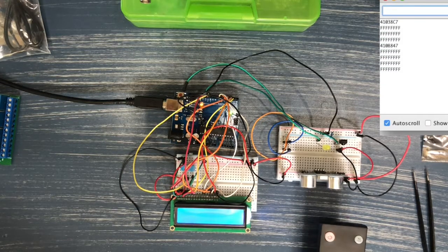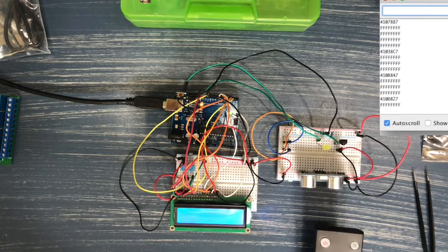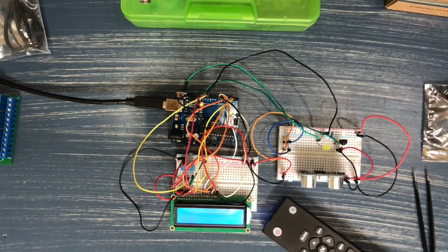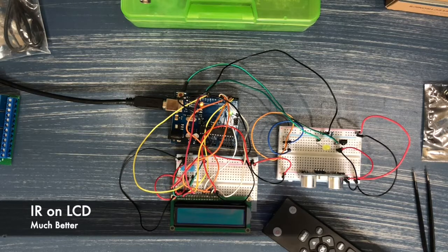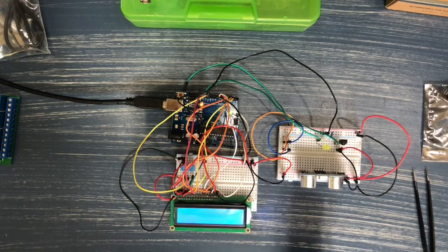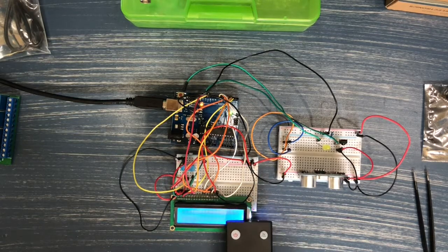There's one, you can see the code. There's a second one, a different one. There's a third one. So each one of the buttons has a different code, and that is what we are basically saying whenever we press a button. Okay, so the IR sensor is able to read that data and decode it and spit out whatever code it was programmed to send whenever that button was pressed. Now we're going to select that code for the LCD screen, upload it to the Arduino, and display it on the screen. And there it is.